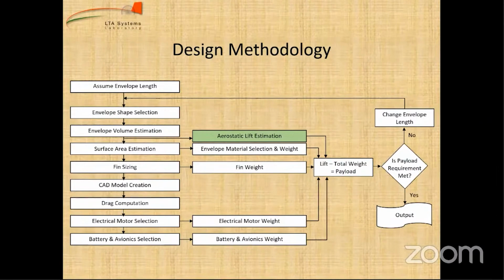So in order to calculate the lift, what should be subtracted from what? Density of air subtracted from density of gas. How will you subtract a bigger value from a smaller value? That will give negative, right? To find the net lift, see the formula that I had told some slides back: V g (rho of air minus rho of LTA gas).